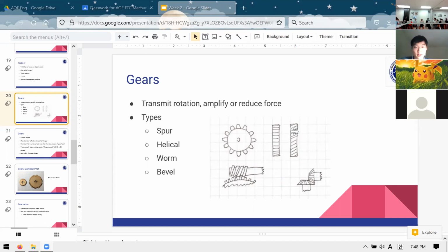When it comes to gears, we have a lot of different types. The most classic one, the one that I just showed you, is a spur gear. These are the most simple kind of gear. The teeth are just cut straight. They look kind of like spurs on riding boots, I guess. Maybe that's why they're called that. That is in contrast to helical gears, which have teeth that spiral. They look a bit like you might imagine the mecanum wheels do, where the teeth of the gear curve along. They have an angle when you look at them face on.